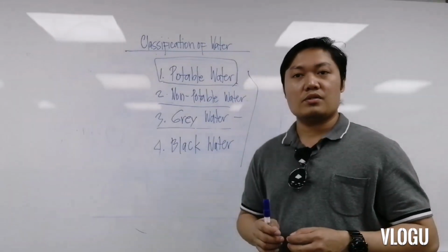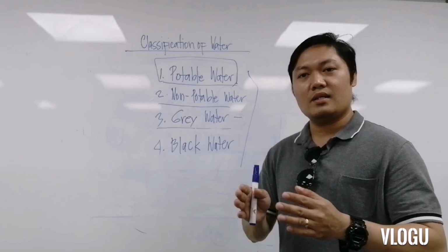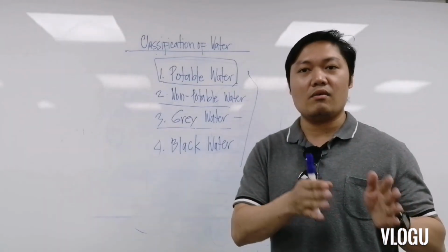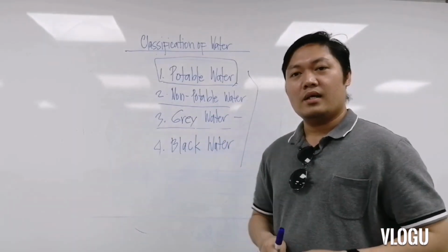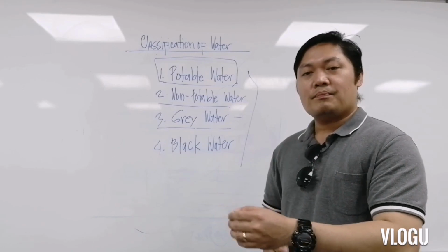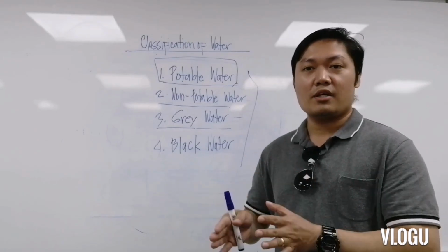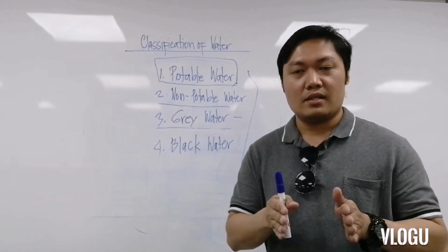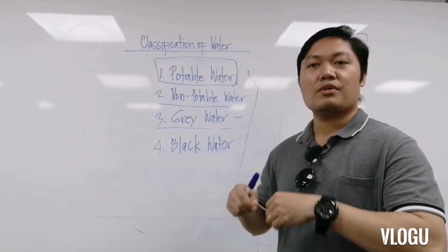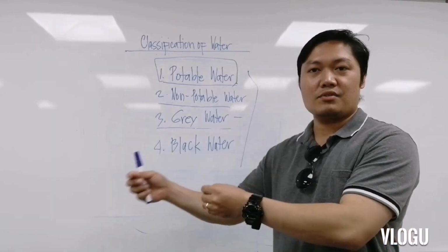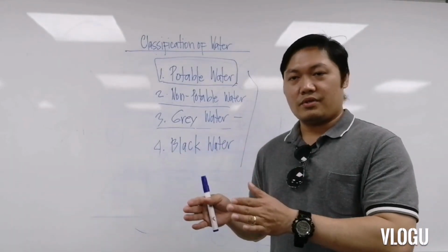At the same time, you also need the method statement. You are going to submit to your project consultant the method statement, the document stating all the works, process, and procedure of how you are going to execute this activity on site. We also have the inspection and test plan, which is a general requirement. It is the document stating all the testing processes used to determine whether the work on site is satisfactory before you hand it over to the end user or the client.